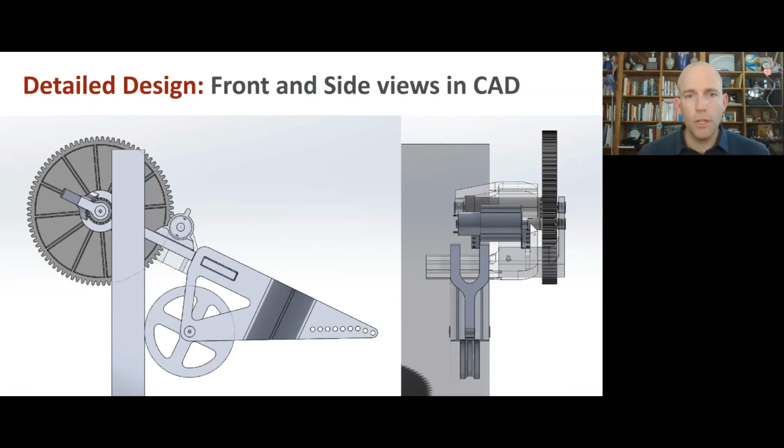So we have the motor here connecting it, and then there's that bushing built into the output stage of the gearbox that provides one of the bearing surfaces, and then on the other side we have a ball bearing there. So that element is in simple support. Also, we avoid having big force multipliers that cause high friction that would dissipate a ton of energy otherwise. And same thing for our passive wheel down here, simple support.